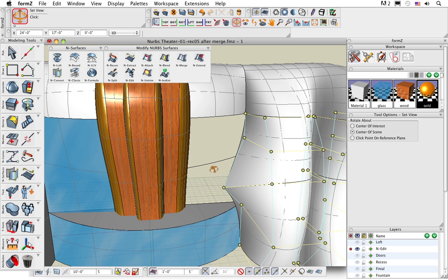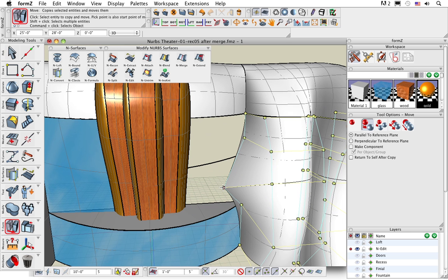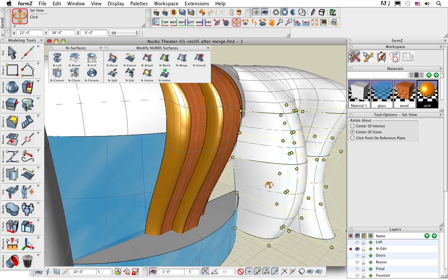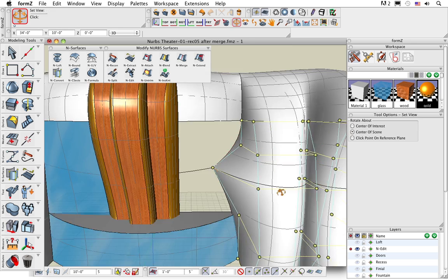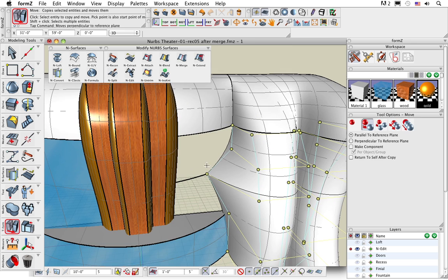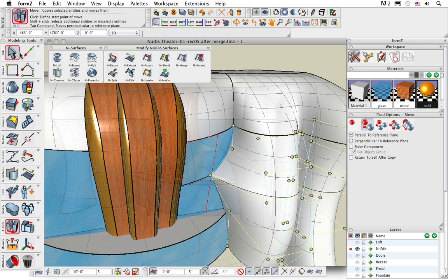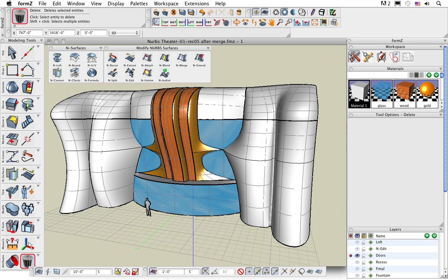So now what I'm going to do is take my control point over here, and I can drag it and snap it right to a position along that spline curve. So the new creased edge in my vertical column can now snap to a specific location right on the front facade of that glass. And then we use the same technique on the gold transition to insert a knot with a kink option. We grab the control and snap it to the other control point position of the other control that's in the vertical column to finish off the rest of the facade.